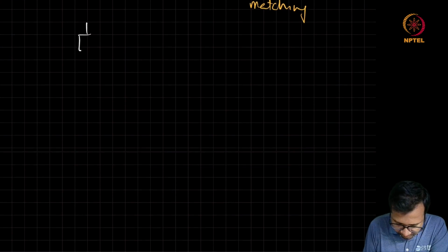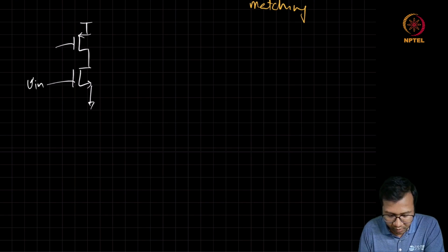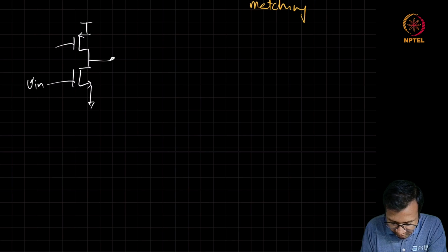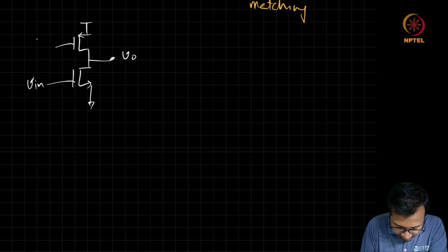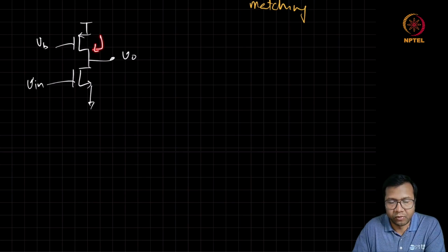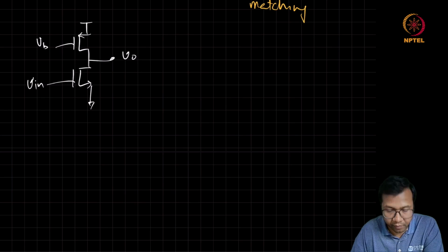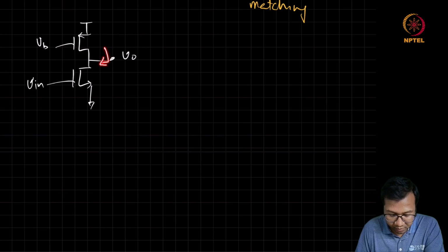There is another practical problem whenever we are using a MOSFET as an amplifier. We'll see that any practical amplifier design will look like this, where the input is applied at the gate, and the output is taken at the drain. The output impedance of such an amplifier can be pretty high because we will also be having some kind of active load on the drain side, and this active load will make sure the output impedance is increased to increase the overall voltage gain.